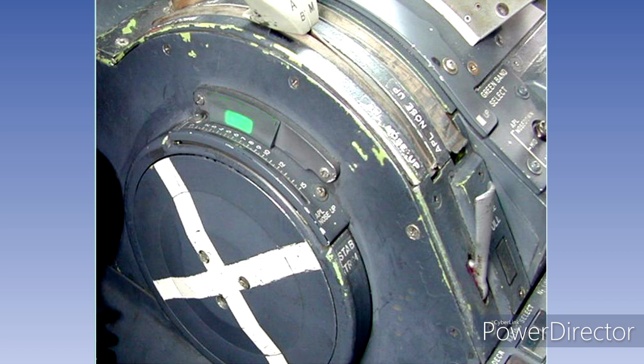In order to ensure that the aircraft will be trimmed in pitch on takeoff, recommended takeoff stabilizer settings based on aircraft weight and centre of gravity position will be given in the aircraft flight manual. The acceptable takeoff range for the stabilizer setting will normally be shown on the stabilizer trim indicator by a green band.